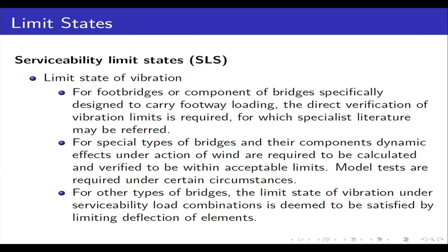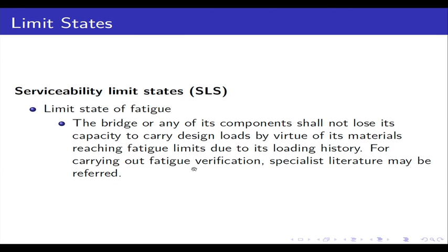Model tests are required under certain circumstances. For other types of bridges, the limit state of vibration under serviceability load combination is deemed to be satisfied by limiting deflection of elements. So, whatever is available in IRC 112, from there I have taken it. So, you can find it there also, because of the checking we have done.